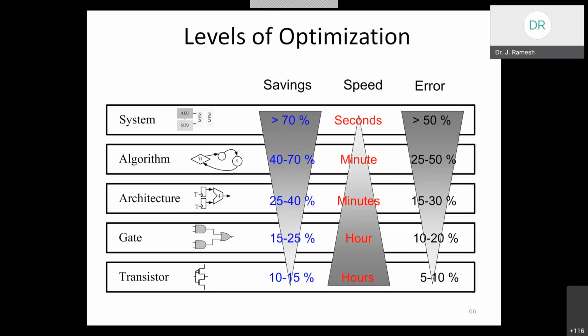Other than that, we can also introduce pipelining. In pipelining, we have a set of data processing elements connected in series, where the output of one element is the input of the next one. The elements of a pipeline are often executed in parallel or in time-sliced fashion. In that case, some amount of buffer storage is often used. That is, we introduce registers in between.